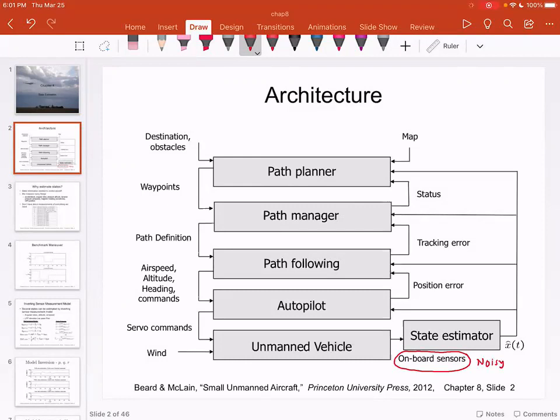measurement. So you will never see an accelerometer giving you a straight line, something like this. You will almost always see an accelerometer doing something like this. So you would see the output of an accelerometer is going to vary as the time goes on, even if input is constant. So here is the problem. Output changes even though input is constant.